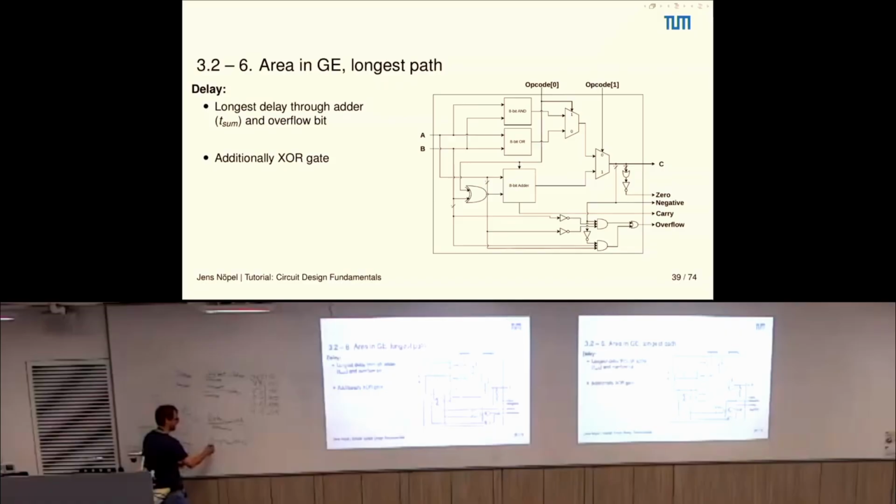And the same thing for vendor B. If you now want to compare those 2 vendors, then you see, okay, the 3-input OR of this vendor is faster than the 3-input OR of this one in relation to the fastest gate.